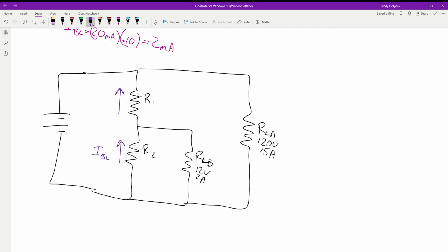Because if we had it up here, we have current coming up this direction from our load. So this is going to be a combination of that load current. So bleeder current does not ever get seen by the load. Ever. It's completely independent to the load.